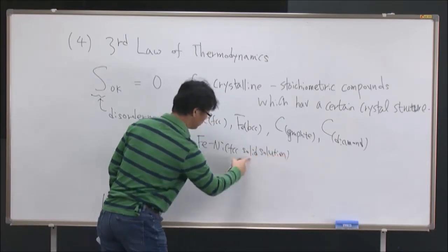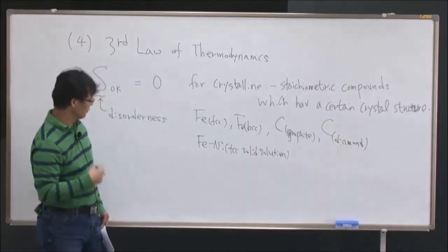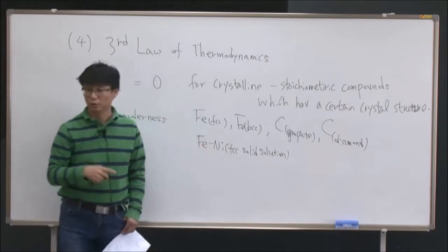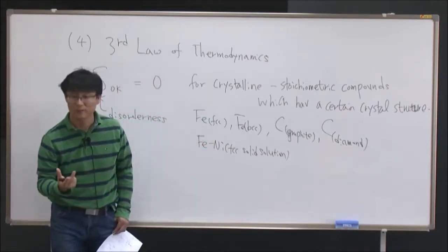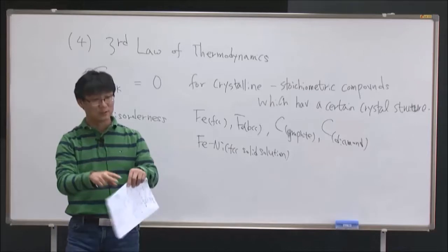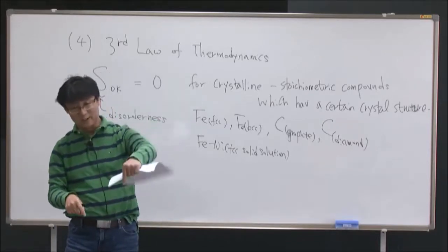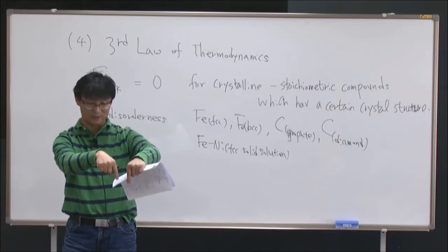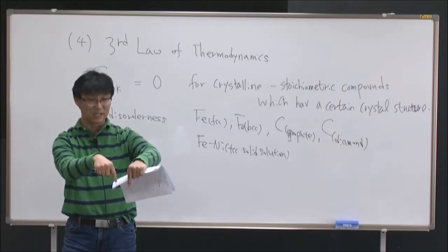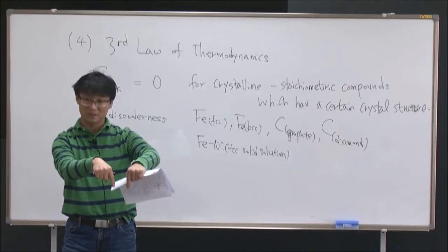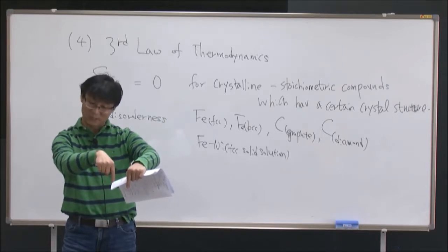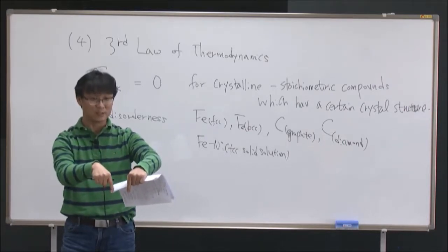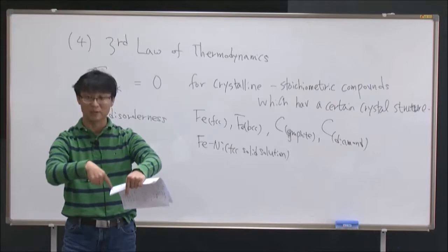it's a solid state, so we call it solid solution. Let's assume I have 50% iron, 50% nickel, solid solution. It's an FCC structure. However, when you mix it, let's assume I have the iron here. The chance to have the nickel next to each other is not 50%. So we don't know exactly whether this position is really occupied by nickel or iron. So there's randomness here. And then on top of that, there's the vibration, of course.